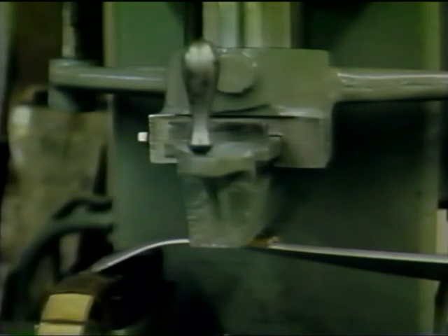A damaged propeller blade may be straightened using large hydraulic presses. Despite the first impression one may get, this is an accurate and carefully controlled process. Specialized tooling and precision measuring equipment permit the repair station to make pitch changes or corrections as small as 1/10 of 1 degree. Face alignment and angle measurements are taken once again to ensure accuracy. This constant checking throughout the straightening and blade angle change will ensure perfection in the finished product.